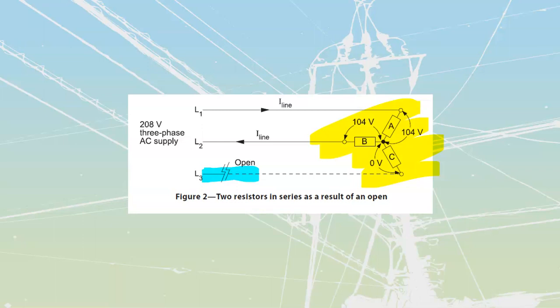We no longer see 120 volts, we now see 104 volts and 104 volts. This is exactly what we just saw with the triangle. These two loads are stretched across from there to there, and because the value from this line to this line is 208 volts, we have 104 volts dropped over top of each one of these. Okay, that's cool for how we get to the values of voltage.